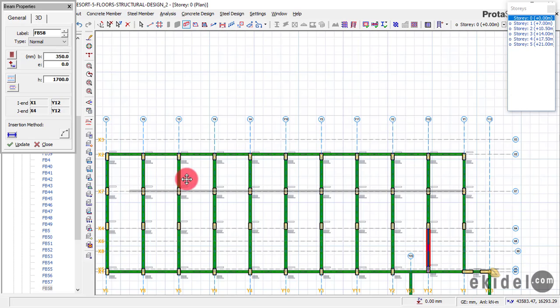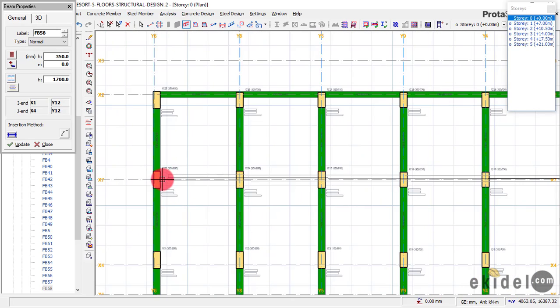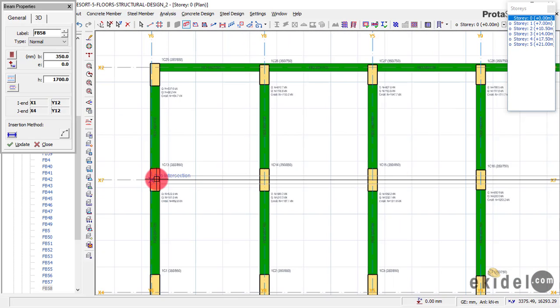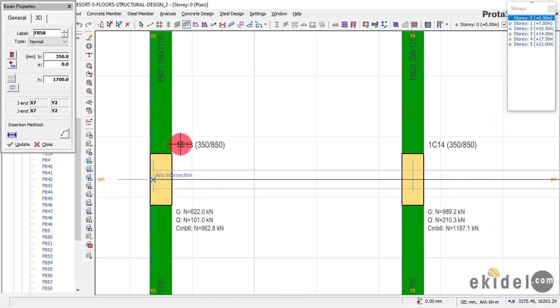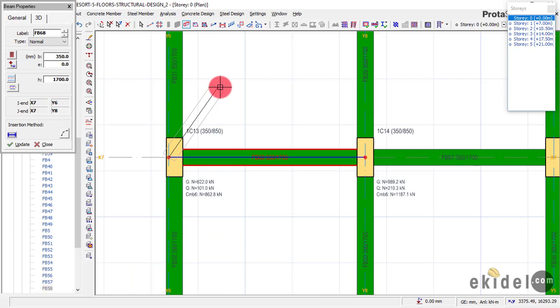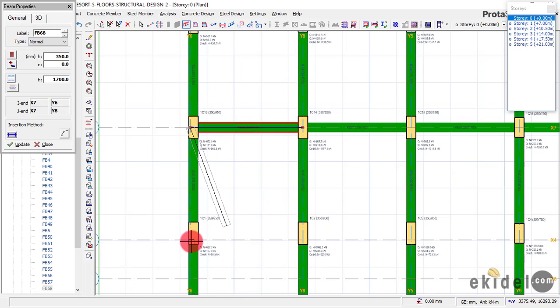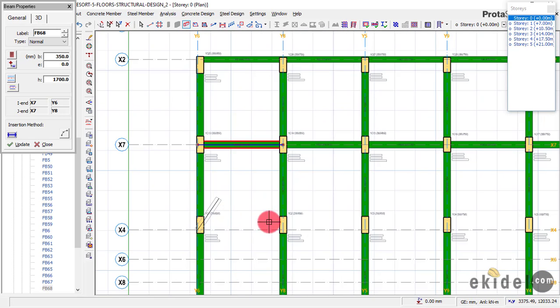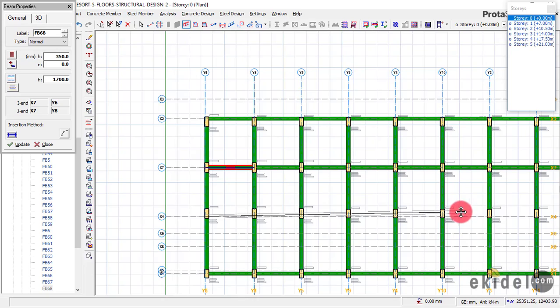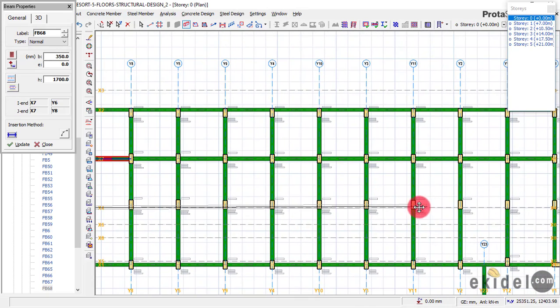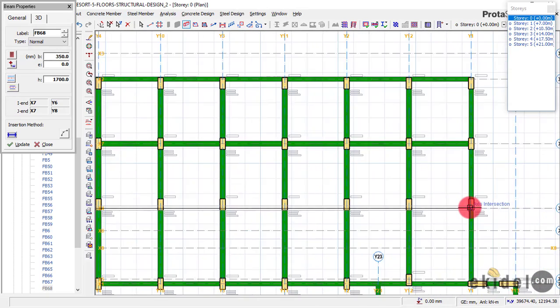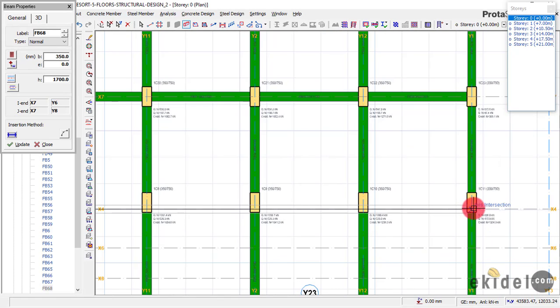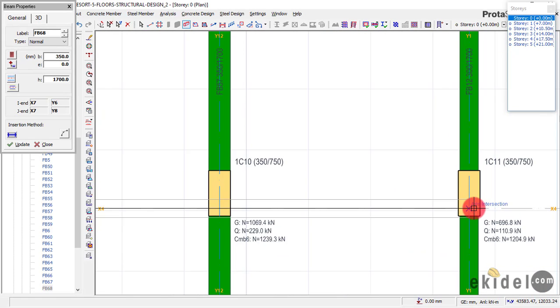Because when you have different sizes of beam width or depth of beam, during the construction, it might cause confusion. So just to avoid that, you just have to use a typical beam width and beam depth for your foundation. Although for your Raft foundation, your beam depth must be the same; the width can change, but the depth should remain the same.